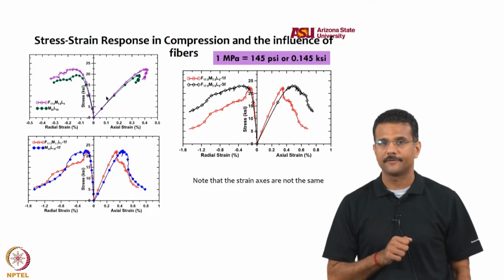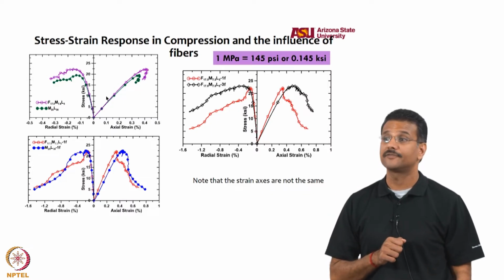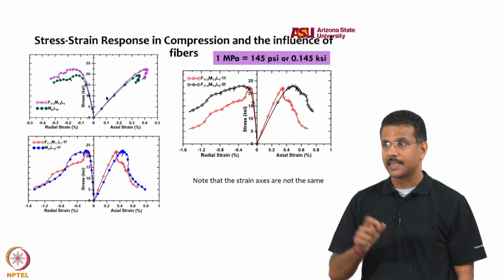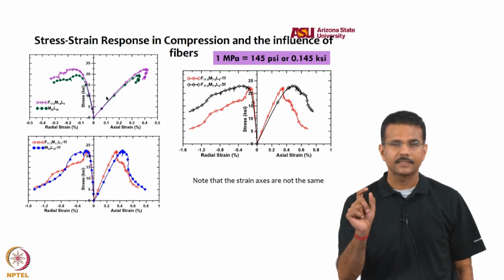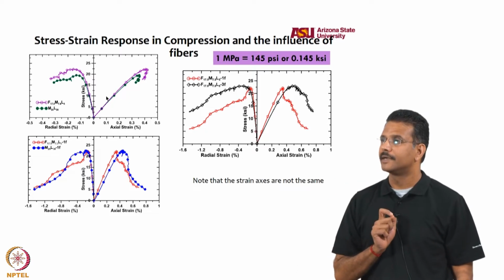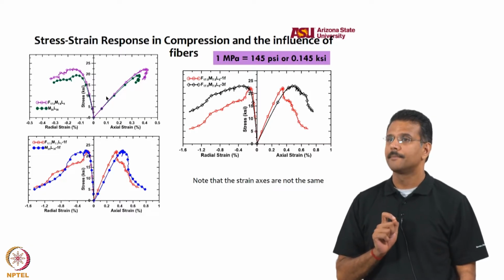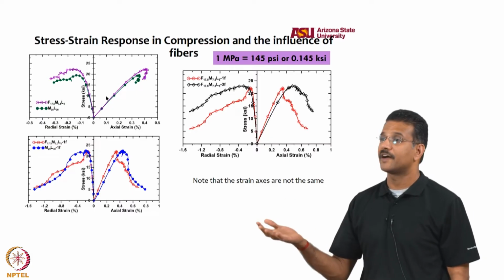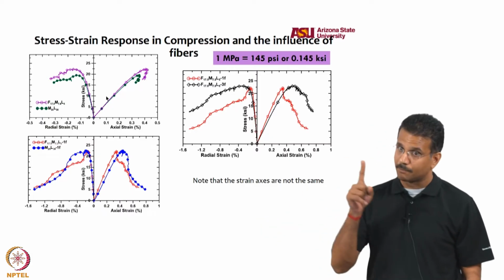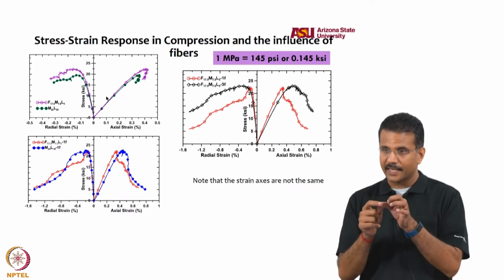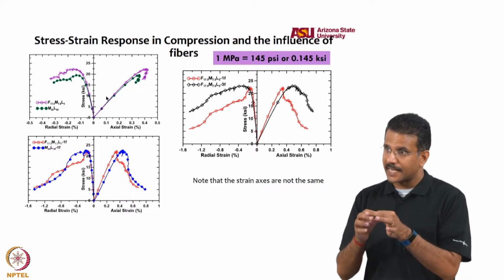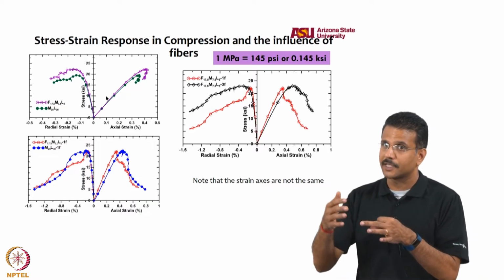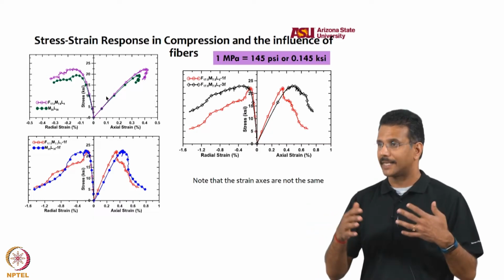That is the trade-off that you make by the addition of aggregates. The larger aggregates, coarse aggregates, are known to give you deflection softening behavior because you create those interfaces around which cracks can propagate and the fibers are not very effective. But if it is a mortar, where the size of the aggregates is very small and fibers can take into account the crack bridging much faster, if you do a mortar you will get deflection hardening.